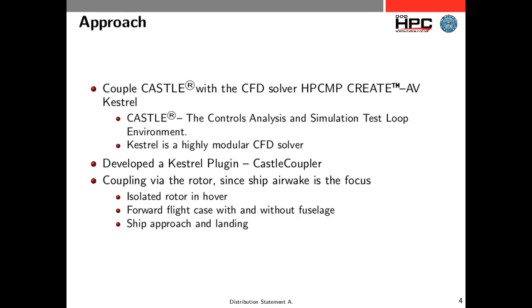So the approach was to couple CASTLE, which is the Navy's manned flight simulation environment, with the CFD solver Kestrel. CASTLE is the Controls Analysis Simulation Test Loop Environment. It's a modular environment where you can have all sorts of different aircraft and models plugged in. And Kestrel is a CFD solver, also highly modular, with unstructured meshes near the body, and the ability to do off-body adaptive Cartesian mesh.